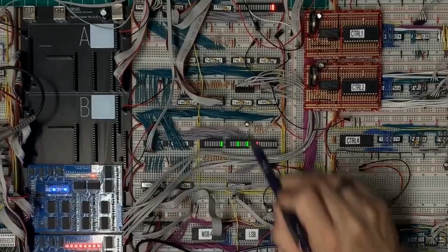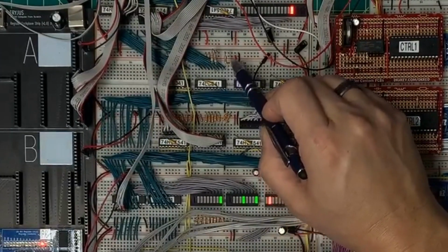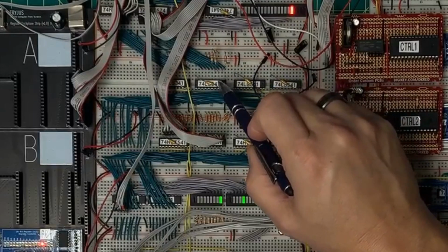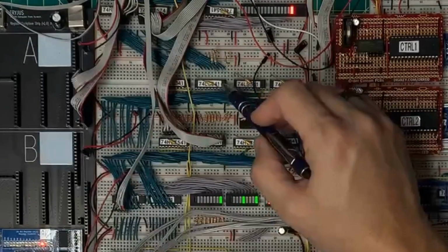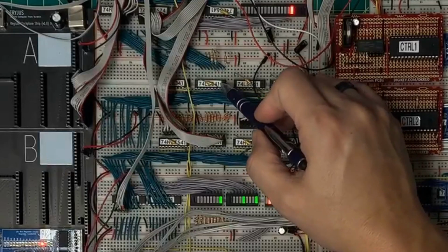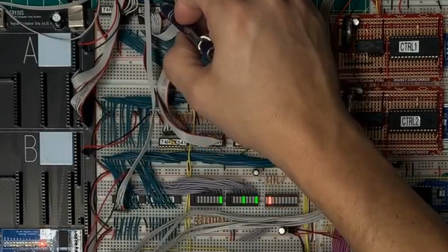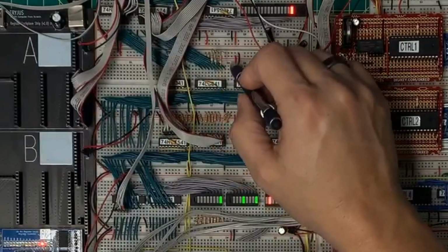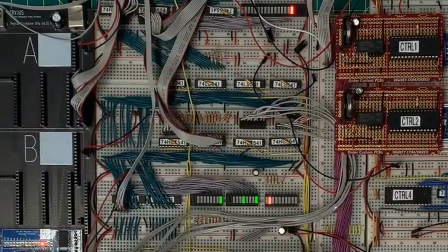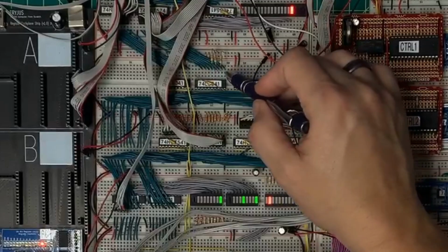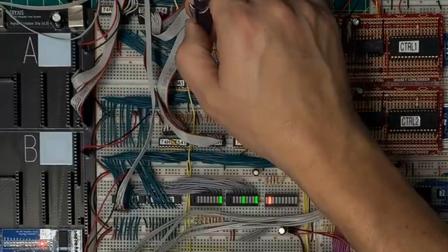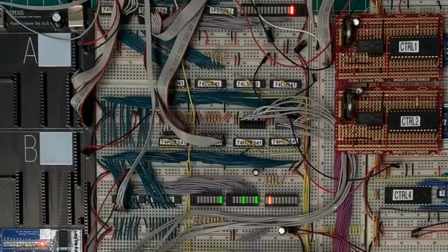Now, why? If you look carefully here, I was playing around with the resistors associated with the least significant nibble on the instruction bus. I call that loosely because there's only two things tied to it, but out of the fetch register asserting onto the instruction register. And I had 4 resistors in here at one point and managed to remove one somehow. Not exactly sure how I did that. And so now I've got a floating line going into the instruction register. These are 2 mega ohm resistors. These are still 1K ohm resistors down here.